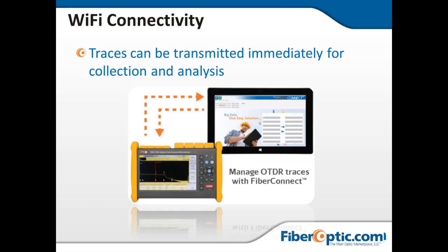One of the things that we're offering at fiberoptic.com is this management of OTDR traces. So what you can actually do from your OTDR is upload it via the Fiber Connect software right into a centralized database that'll allow you to store and document your network. So if you can get that Wi-Fi connectability, that's a great feature, and I would certainly recommend it. Also, if you can't, one of the things we're showing here is you can also plug into a tablet that has Wi-Fi at least, and use that tablet as a way of connecting back into the system and uploading your traces.